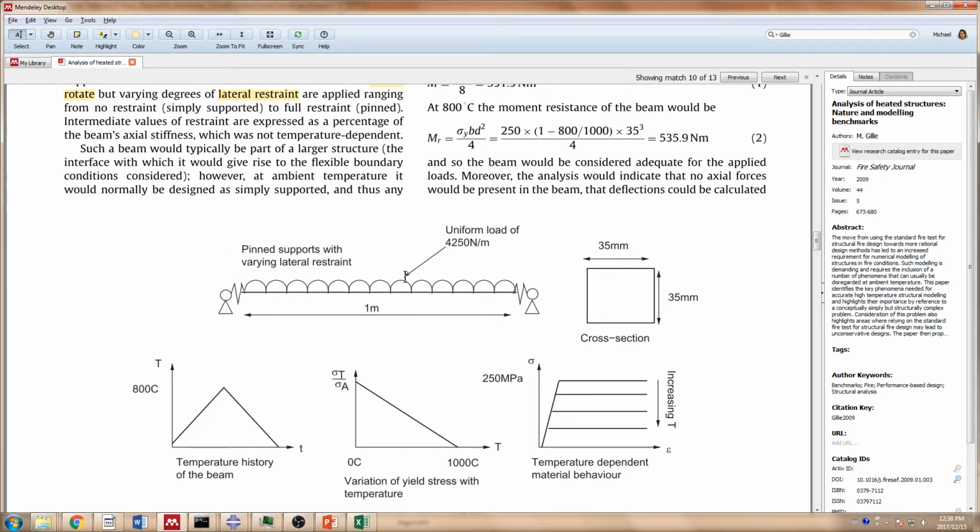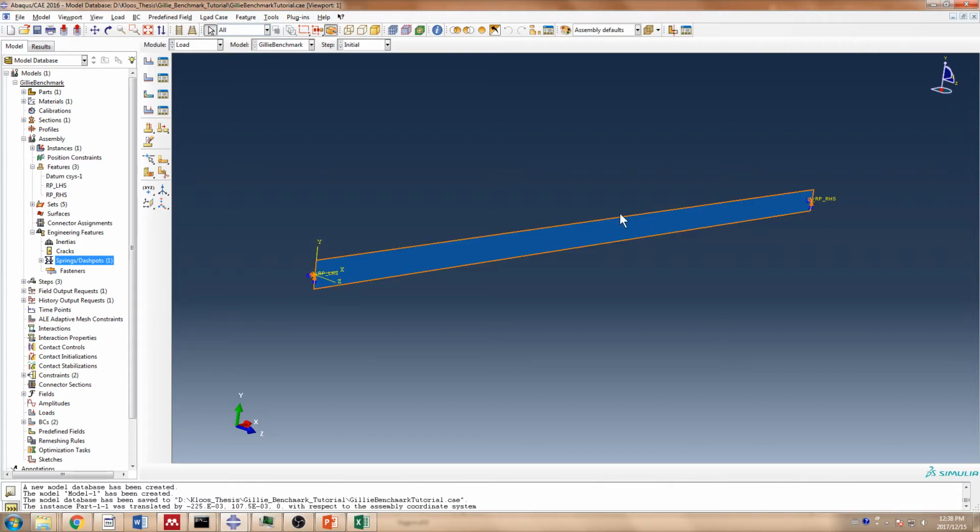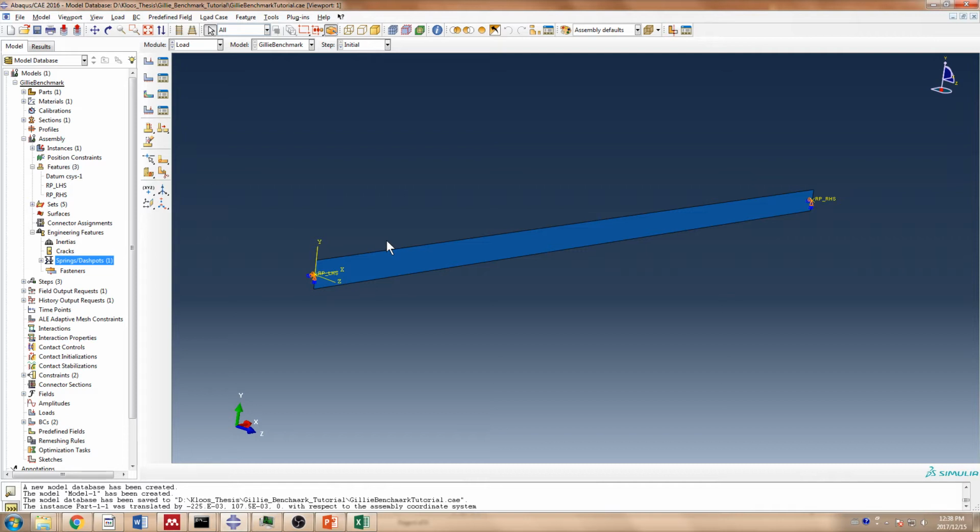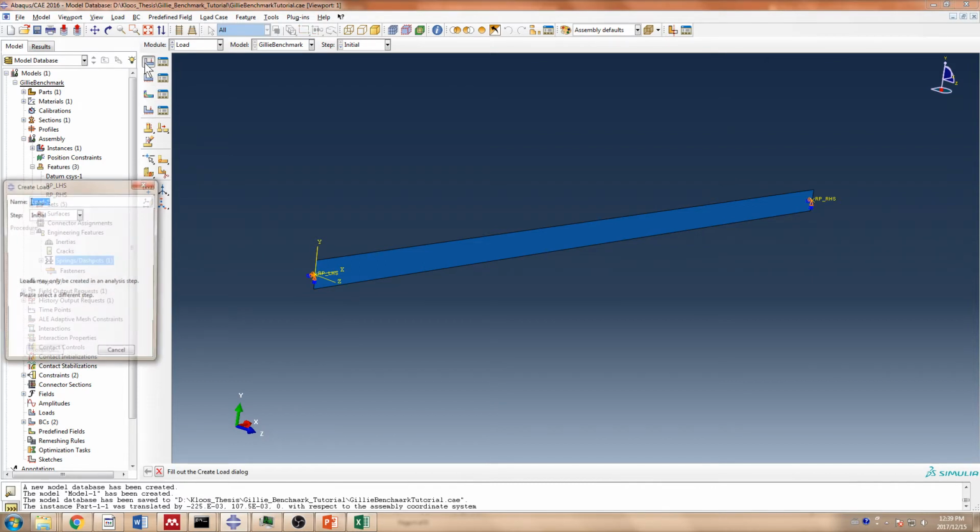So there's many ways to apply a load in Abaqus. The problem with applying line loads on shells is that you can only do shell edge loads, which would work in this case, but if you were to sketch more complex sections such as I-beams, you sometimes struggle to do that. Also, the shell edge load follows the rotation of the part, which can become complex in fire if there's very large deformations. So the way I'll be choosing to do will be a surface traction over the side of the beam. You could also partition your beam and create a series of point loads, but in this case I'm not going to show that because I'd have to create a whole bunch of partitions, which is going to take some time. So let's do the surface traction.